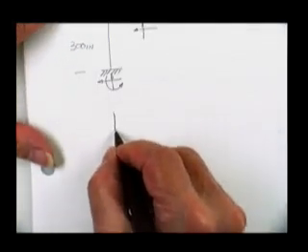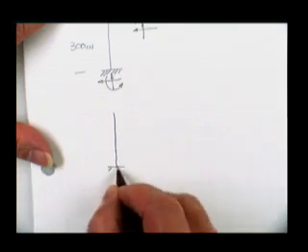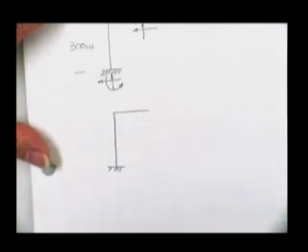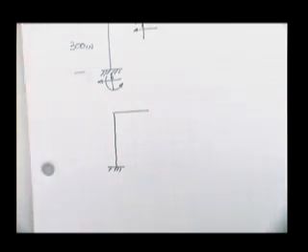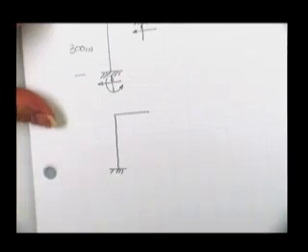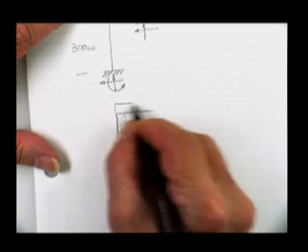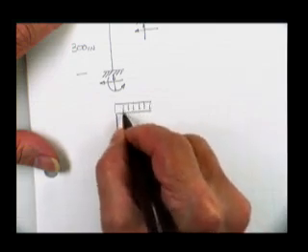And so what I'm going to do now is just jump ahead and tell you that what we will be doing is you will be taking some of those sad reactions off of there, those things we can't find, and letting the structure deflect however it wants to, even though you don't like those deflections. And you will solve for those deflections you don't like, and then we will come up with ways to make them go away and get the original structure back. Here is the real structure.